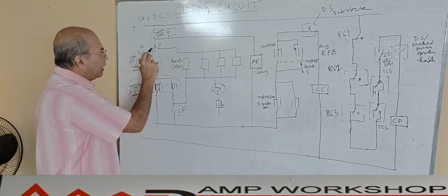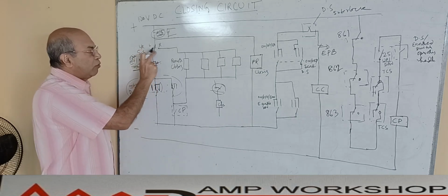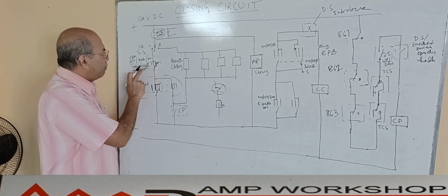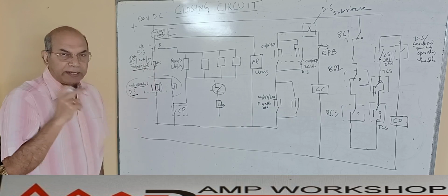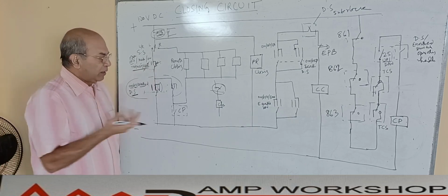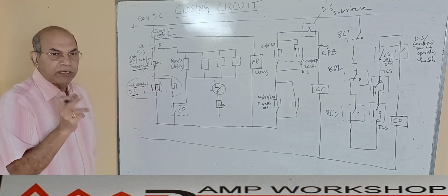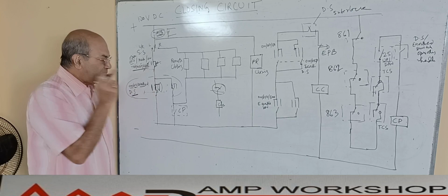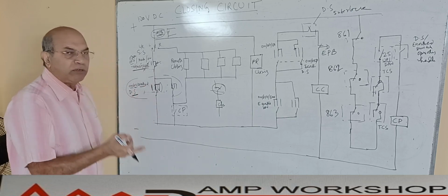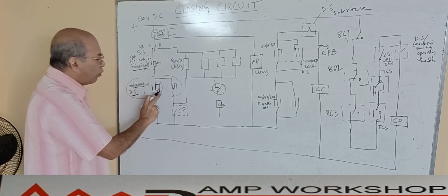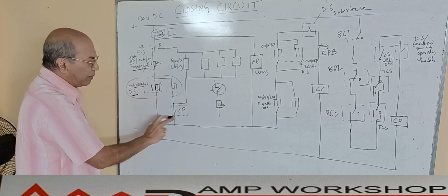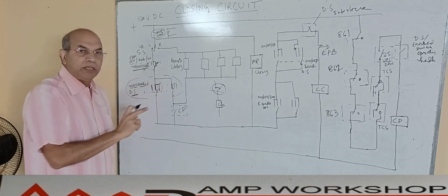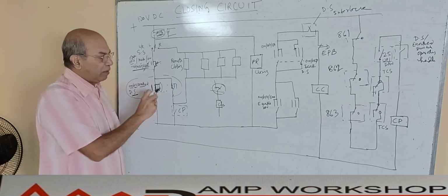The local remote switch is in the local position. In the local position, I am going to close the breaker. So I put the switch in close position. At that time, I am making sure the isolator is in the right position, means either isolator is off or isolator is on. Isolator off position will be used for the testing purpose of the closing circuit, and isolator on position will be used for real powering of the circuit.